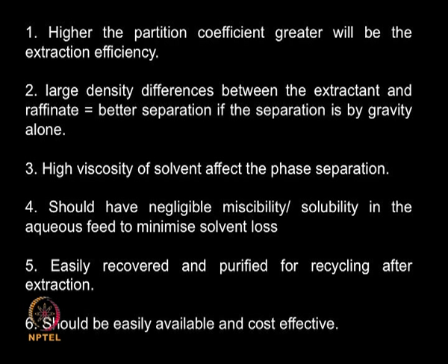Now you should be able to, after the extraction, remove the solvent from the solute which has been used for extracting, because your solvent has to be purified and again recycled for further extraction, because the cost plays a very important role in your downstream processing, and the solvent recoverability is a main issue in the overall operating cost. The solvent should be easily available, we do not want to use many exotic solvents because then it may be very expensive and it will add to the extraction cost.